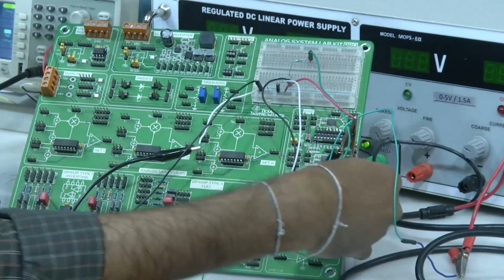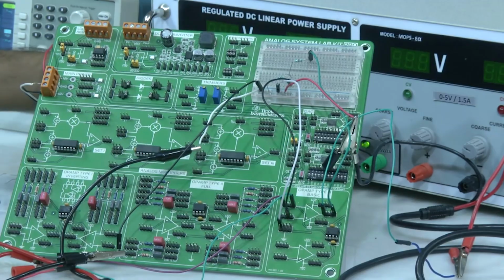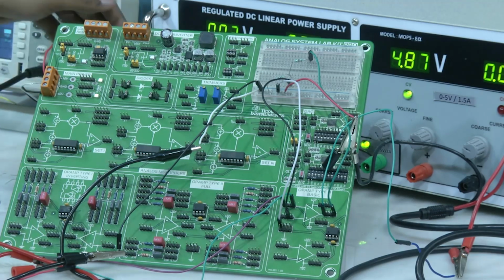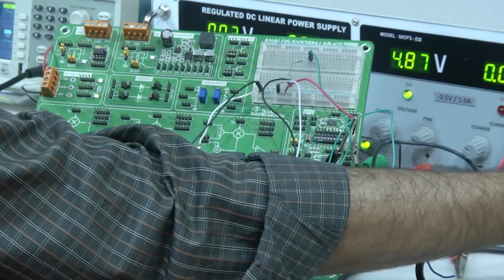So, how does it work? When the input voltage is greater than plus 4.6875, the output should be minus VCC, and again when the input is lower than minus 4.6875, then the output will become plus VCC. Now, the connections are done. When we look into the CRO,